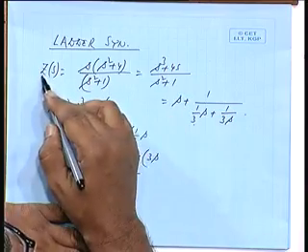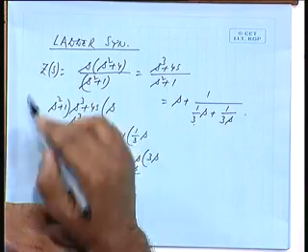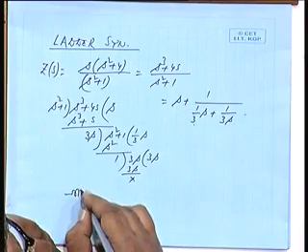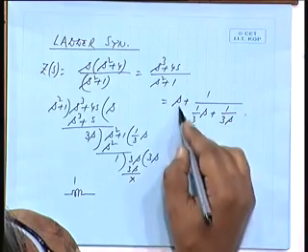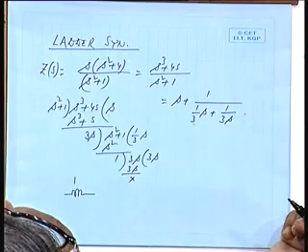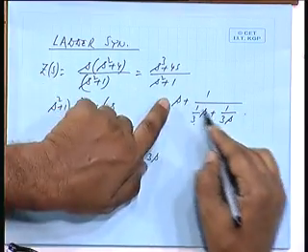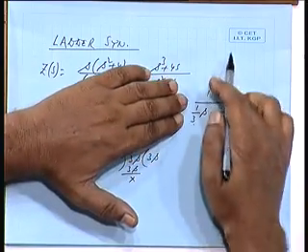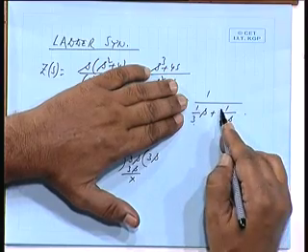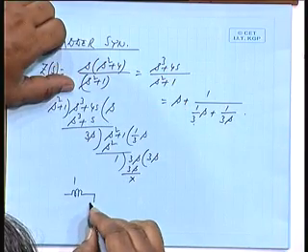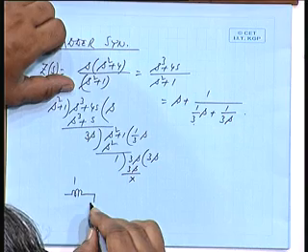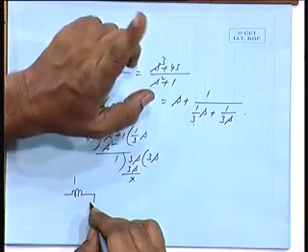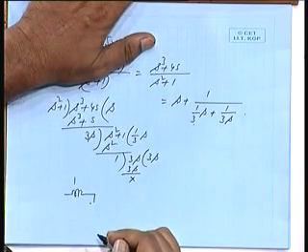Then we have started off with Z(s). So this is an impedance, this is an impedance of 1 Henry. Z(s) is equal to this much; this is 1 Henry, then it is 1 by this. So what is this? An admittance. Then it is some admittance, part of which I have realized as 1/3 s. 1/3 s is the admittance of 1/3 farad.